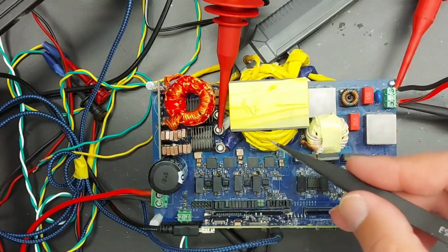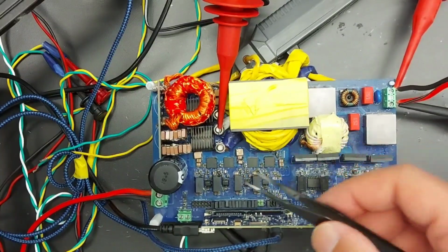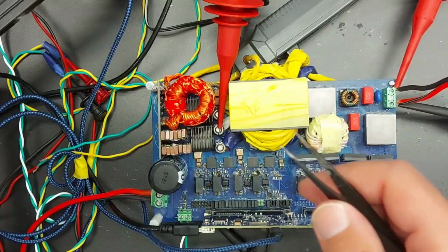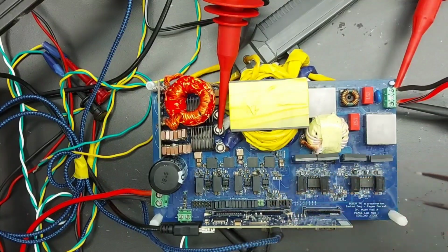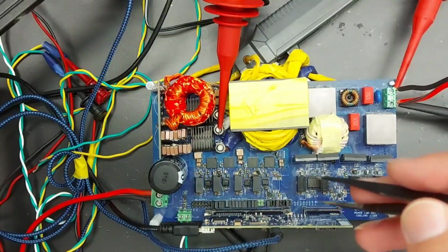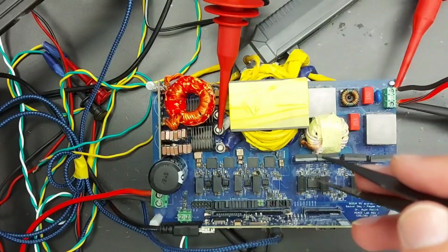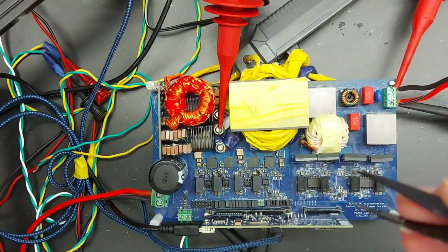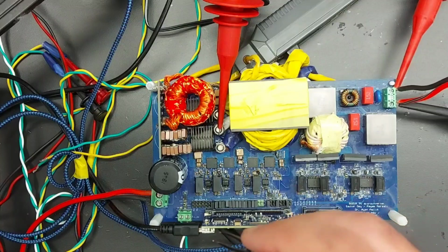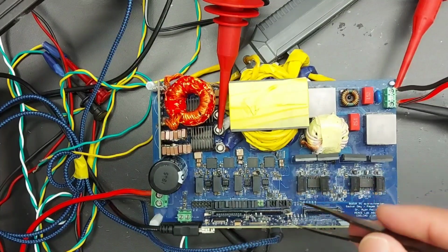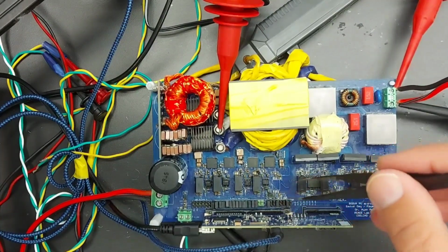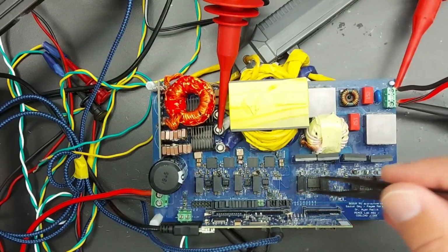Once we have obtained, in an offline manner, these optimized values of delta 1, delta 2, and phi over the 60 Hz line cycle, we can get the regression model of these values and feed the equations for delta 1 and delta 2 to this microcontroller. However, phi itself is controlled by the closed loop control.